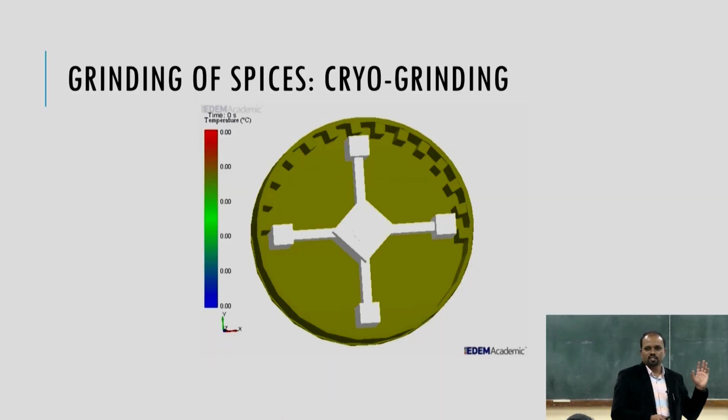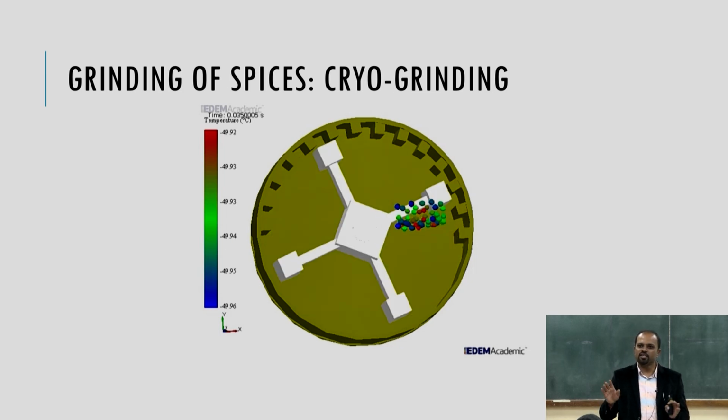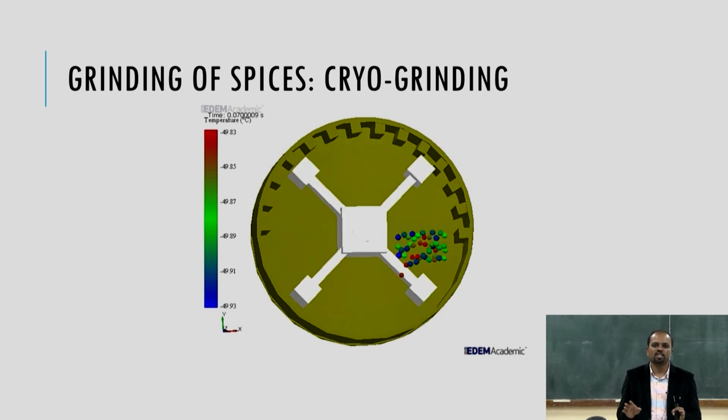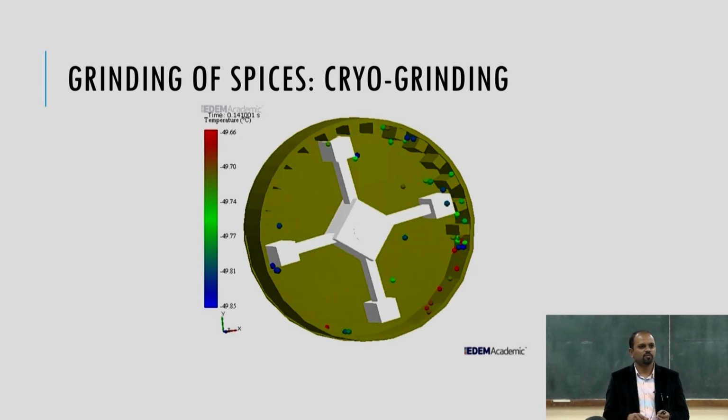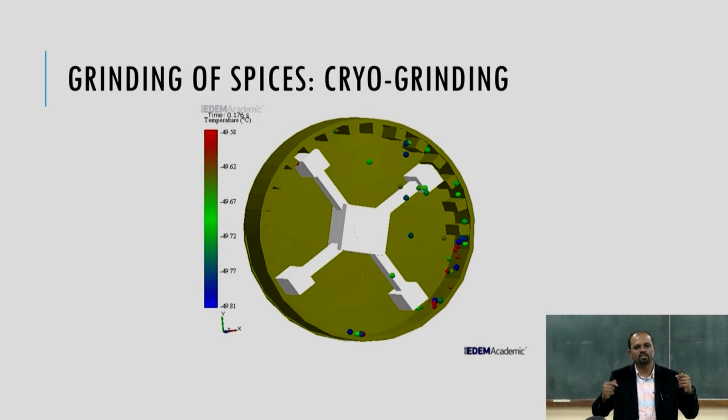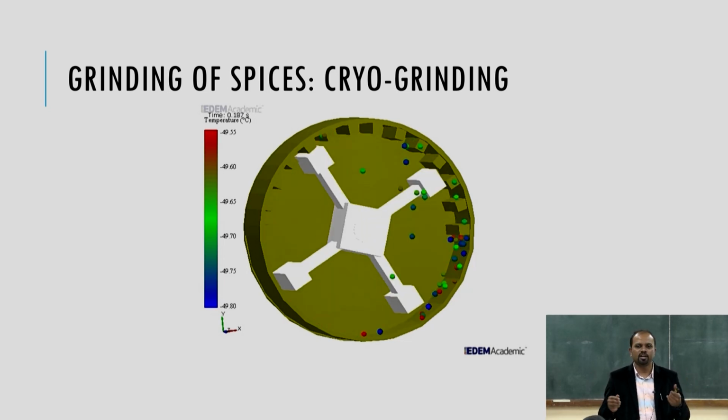Based on this breakage study, we find that within this simulation time of 5 minutes, for the initial 0.2 seconds we assume the particle as a whole particle, and after that there is some reduction in size, then again a reduction in size, and we measure the temperatures. There is a variation of around 25 to 40% between the simulated and the actual results. The temperature is measured by placing thermocouples on 3 sides of the mill: left, top, bottom.